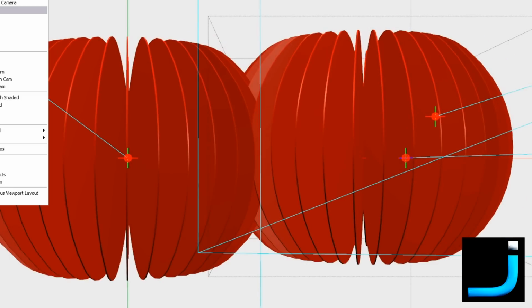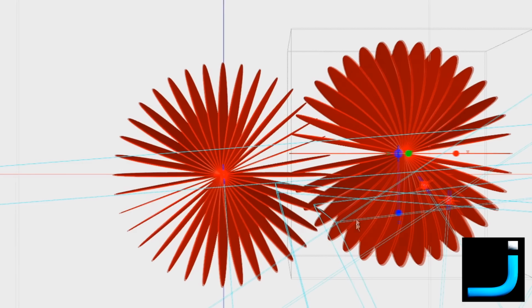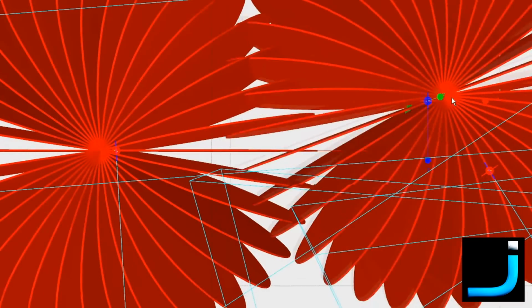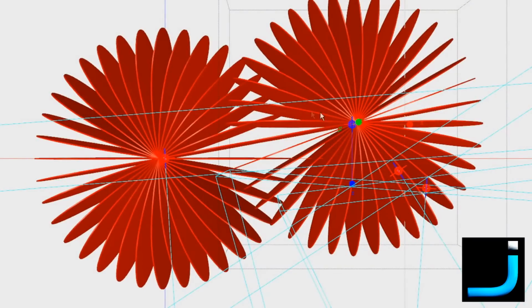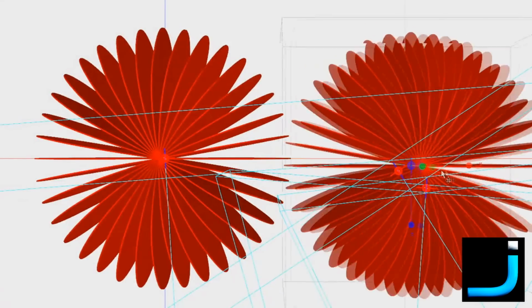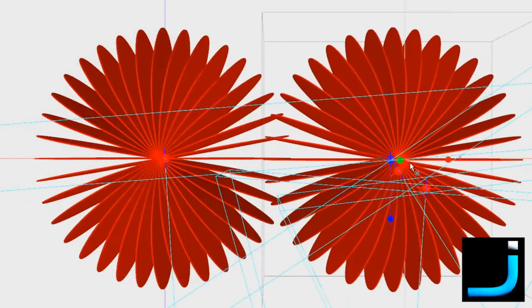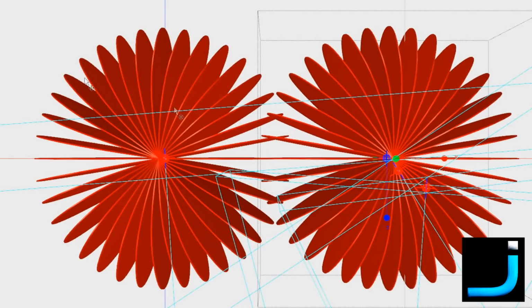And again, if we look from above, we see that shared cross-sectional area is massively larger. So that loss of gain when we mismatch the polarizations can be extremely costly in our range. And you get a massive amount of interference.